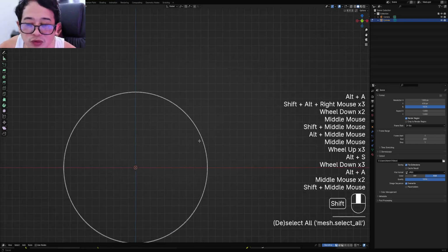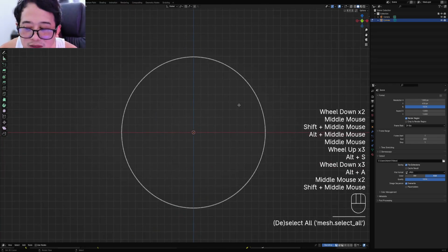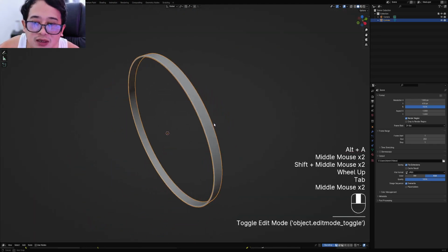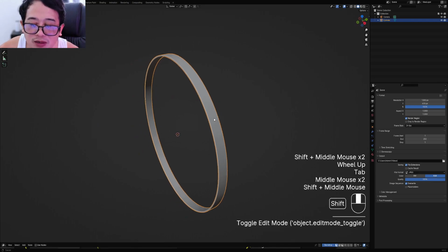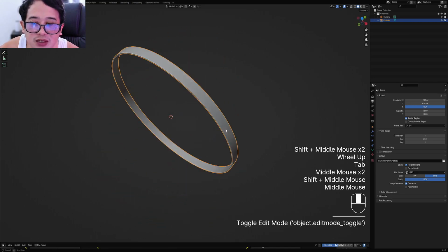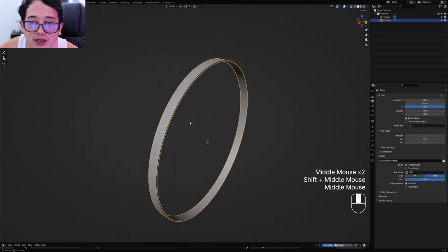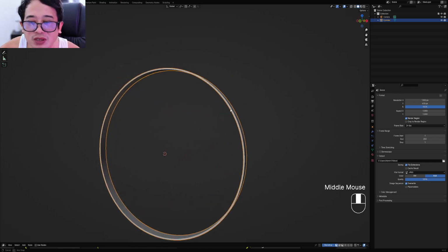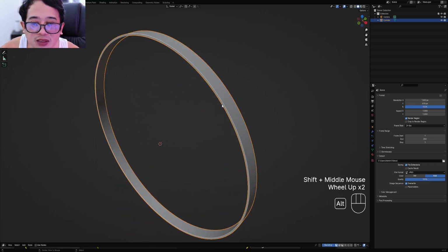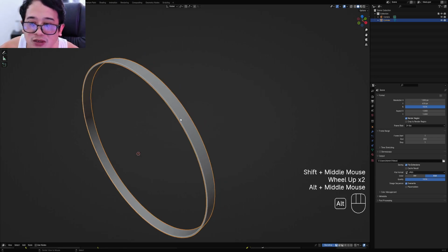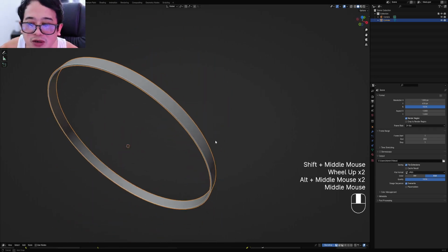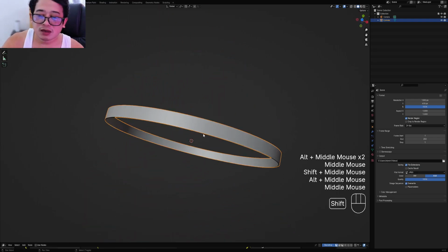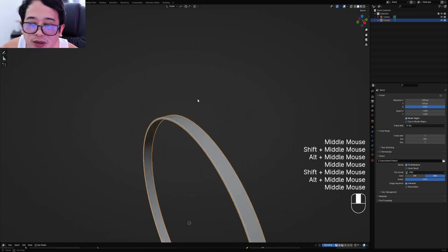Okay, so navigation wise, let me just tell you what I'm using for navigation. To create a pivot point for the rotation in the viewport, you can see that it's rotating somewhere. The pivot point is somewhere in open space, but you can Alt middle click on a surface and that will be your new pivot point when you rotate the viewport.